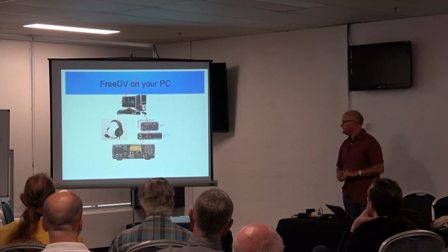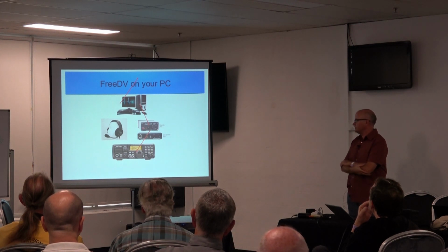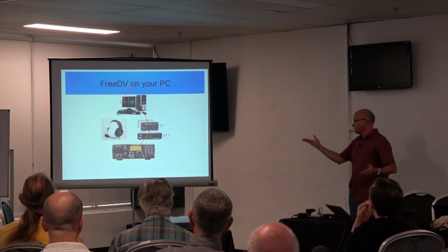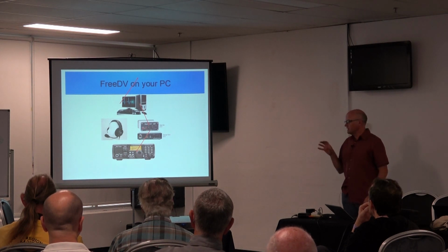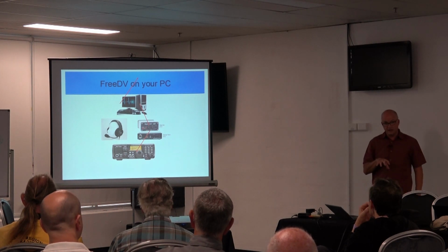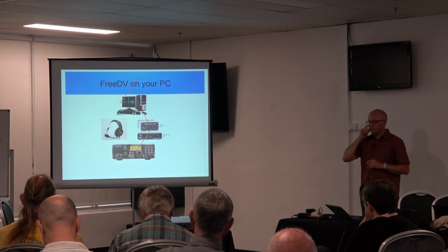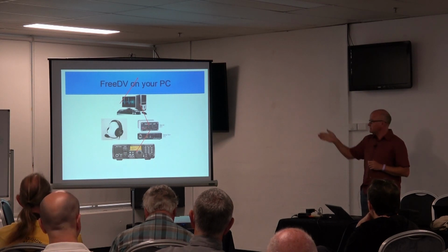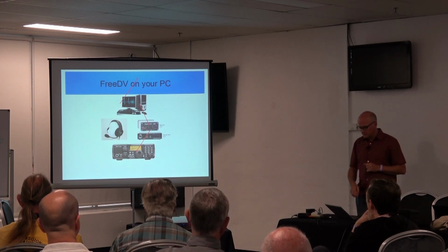The way you hook it up is you take your regular HF SSB radio and you connect it via some sort of sound interface, such as a SignaLink, or some radios have a USB sound card built into them these days. Unlike other digital modes, you also need a second sound card, where you put sound into the system. So it needs 2 sound cards, and we typically use a USB headset for one of those and your rig interface for the other. So that's the sort of hardware you need to get going.